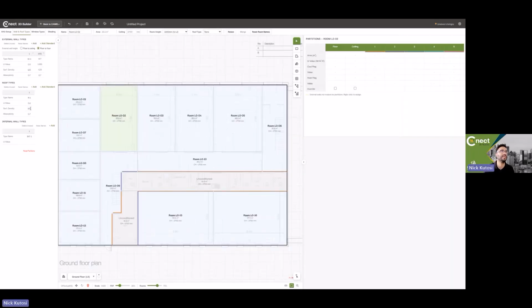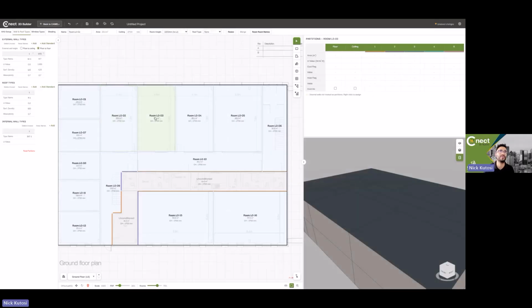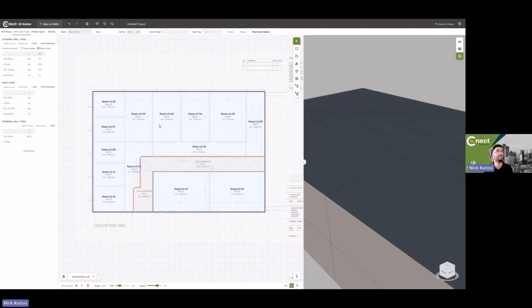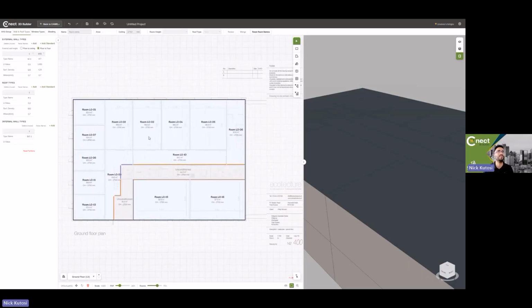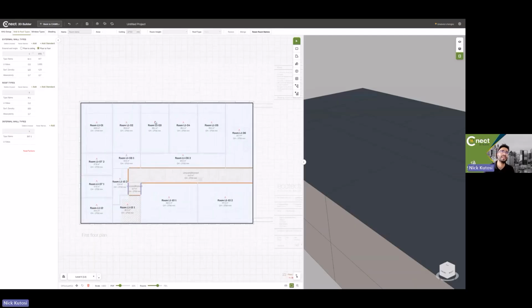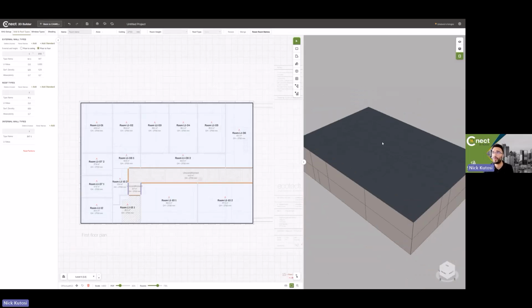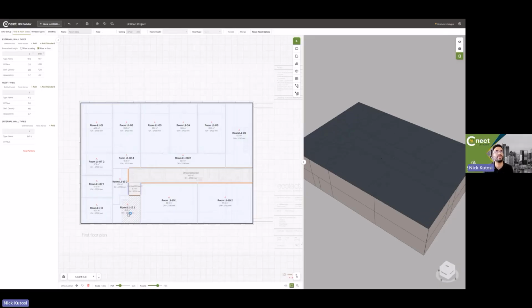To change the roof type assignment, you click the room itself, and then you'll see roof type is one of the properties up in the room properties bar here. So I can assign that as R1, for example. Although there is no roof on ground floor, perhaps if I jump up to level 1, I can better show that. So you can see any rooms that have a roof on it have this little red hat on top of the room name. They also show up as a darker sort of bluey gray color on the 3D view.